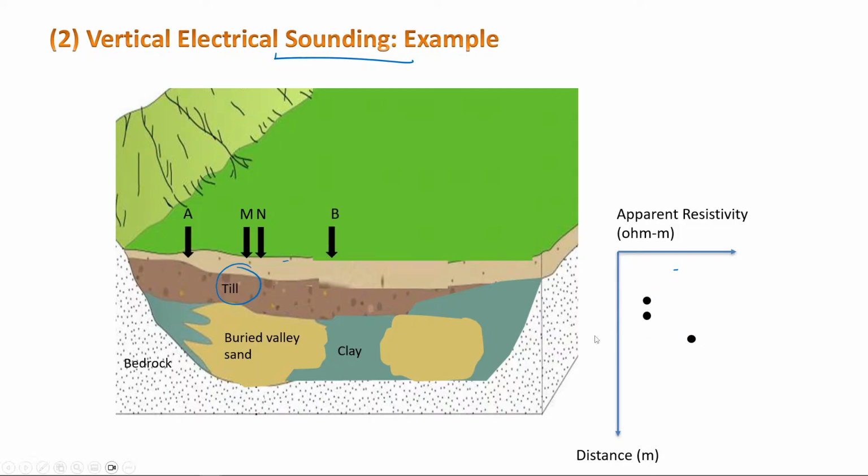Then if I go further, see now I'm measuring at this depth here. And if I go even further, then I would be measuring at this depth here, in this borehole. So this one is called sounding. And the previous one is called profiling. I'm getting this profile.